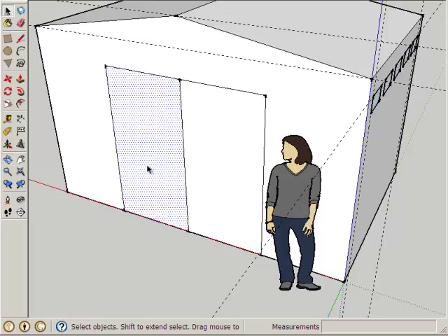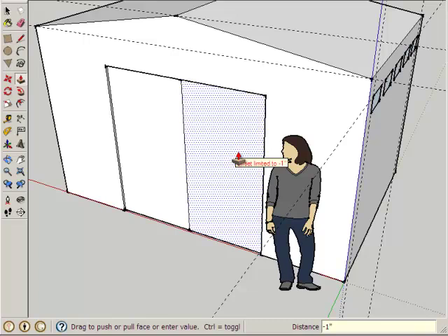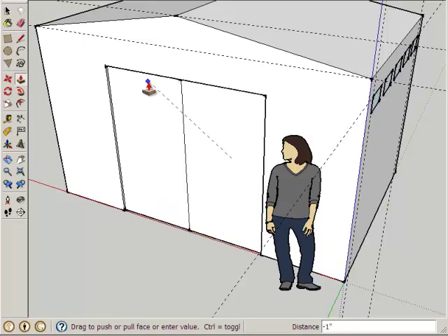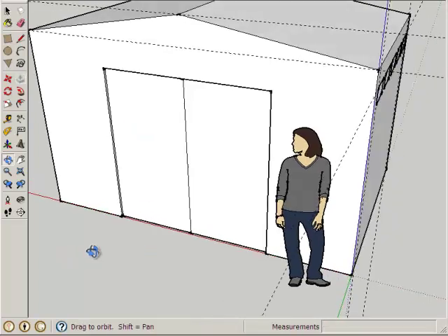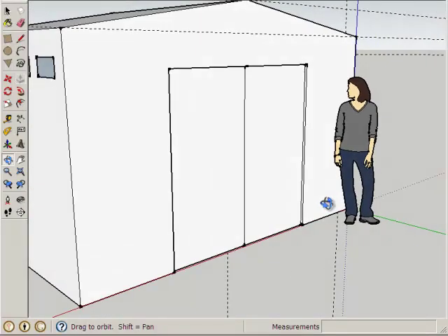For the sake of appearances, I'm going to use the push-pull tool. I'm going to push this door inwards, say 1 inch. Press 1. And I will push this one the same distance. You'll notice it says offset limited to -1 inch. It's going to move in until it runs into the next face, or I can force my move tool to index against the face, and it will match up to that one. So click, and there we have our 1 inch indent.